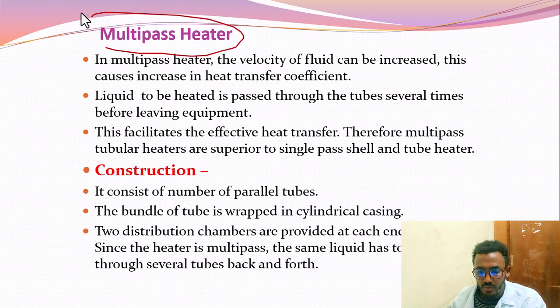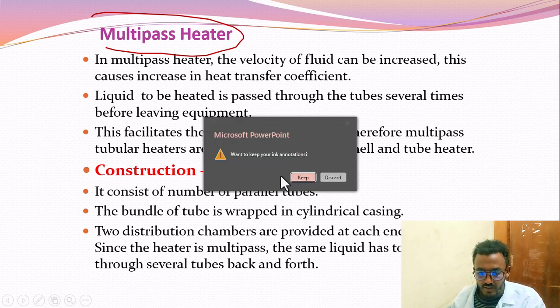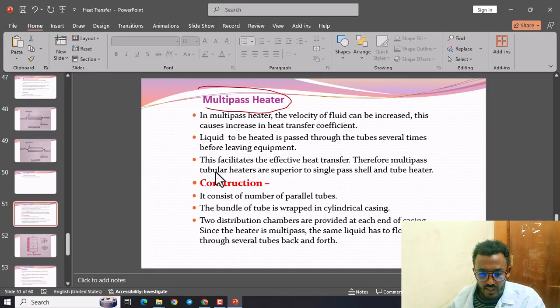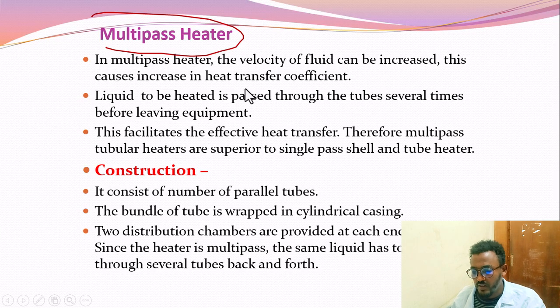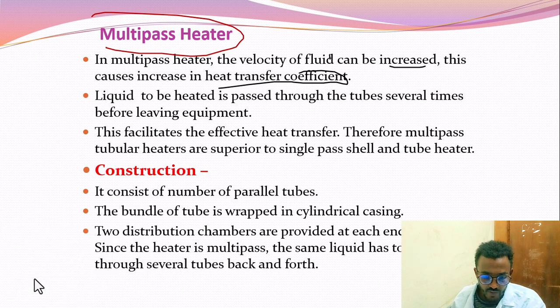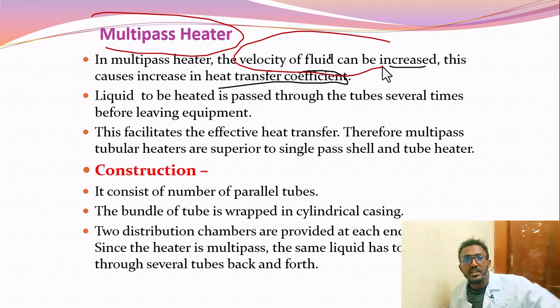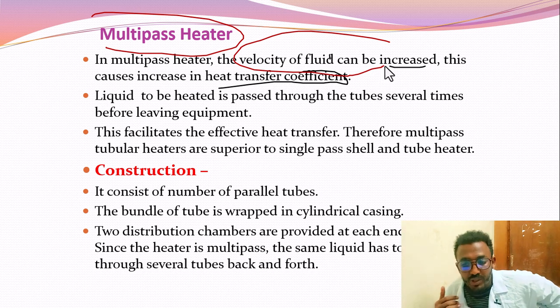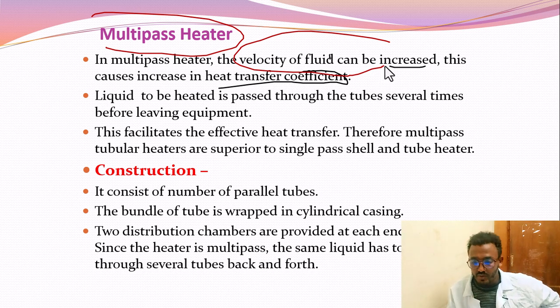And the other one is the multi-pass heater. In a multi-pass heater, the velocity of the fluid can be increased. This causes an increase in the heat transfer coefficient. So we can increase the volume of the fluid, and if we manage to increase it, what we are doing is increasing the heat transfer coefficient.